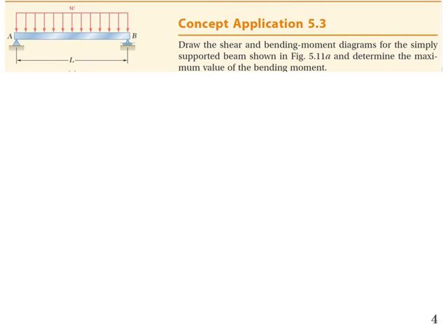Now we have a simply supported beam with a distributed load W, and we have to draw the shear force and bending moment diagram. First we have to find the reactions at A and B. You can easily find them by taking this beam as a rigid body and putting the reactions over here, A and B. RA will be equal to RB, and that is equal to WL by 2.